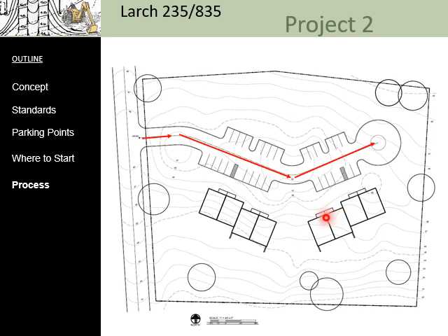So what you're going to do is you're actually going to play this game where you get an elevation here, work your way from the center to the edge of the parking, work your way from there to the building, jump off the back of the building 9 feet, see how it works. If it doesn't work, you're going to go back and change something. The easiest thing to change is adding stairs. After that, you look at changing the slopes between the building and the parking lot. After that, you look at changing the slopes in the parking lot. You could even add retaining walls if necessary.